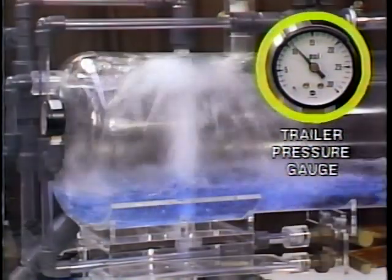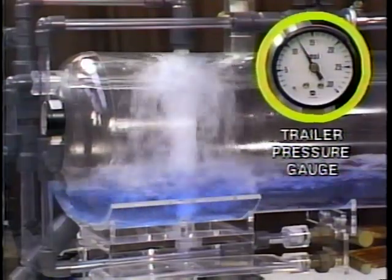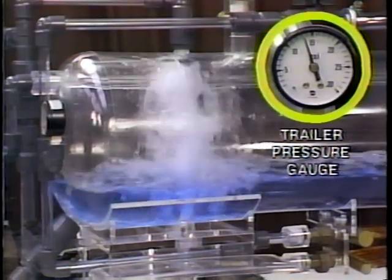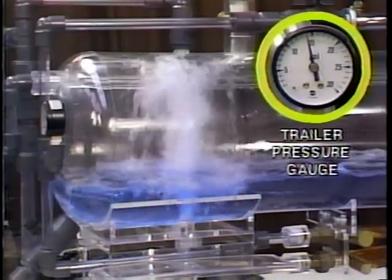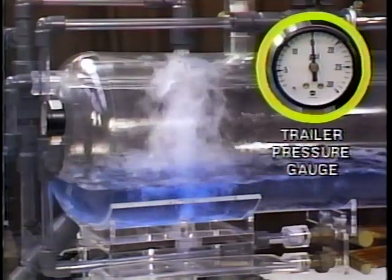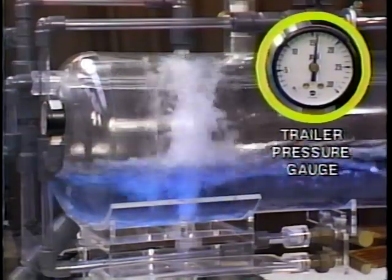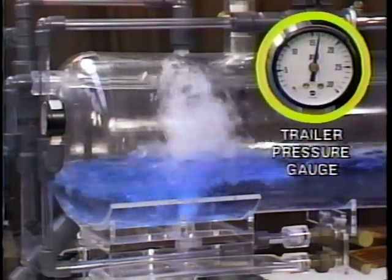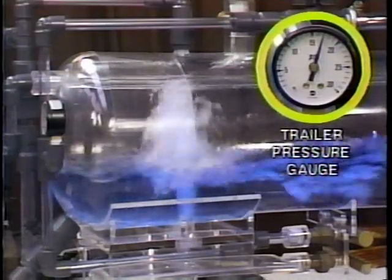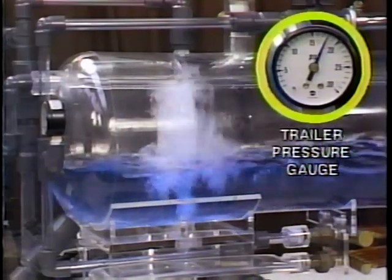The pressure increase is the result of the inner vessel cooling down. This action causes the liquid to flash or boil as the heat is transferred to the liquid. As the liquid level rises, it acts as a hydraulic piston, trapping and compressing the gas above. If we were to continue filling in this mode, the inner vessel pressure could rise high enough to lift the safety valve, causing an uncontrolled release of the product into the atmosphere. To prevent this occurrence, the trailer vent valve should be left open when bottom filling to allow the gas and heat to escape.